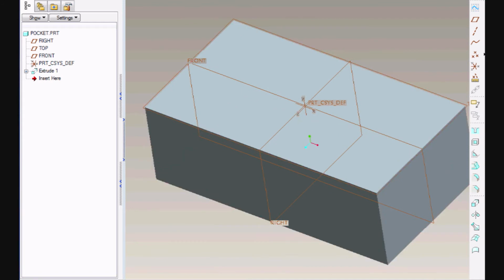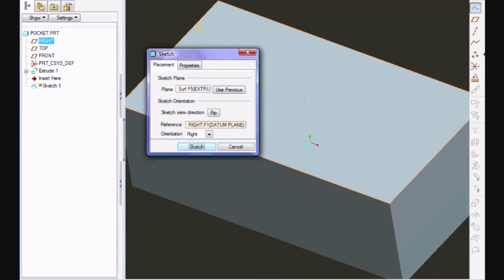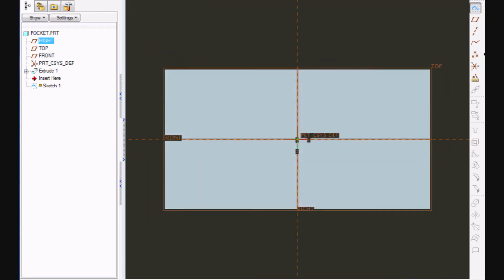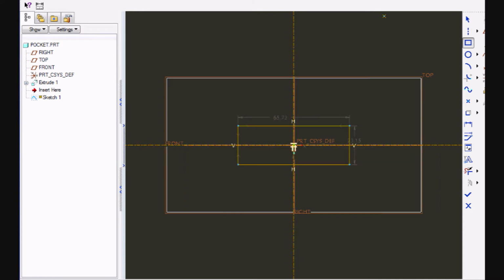When you use a ball nose cutter, the idea is to give a first sketch, what you call a swept profile, and then a cross section for the profile. The cross section will be a J. First I will try to make it symmetrical. It is always good design practice to make it symmetrical with respect to the component.